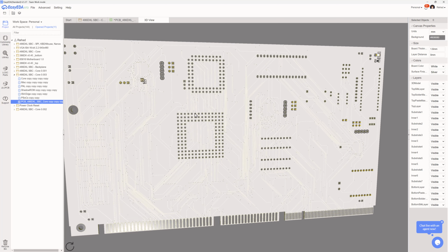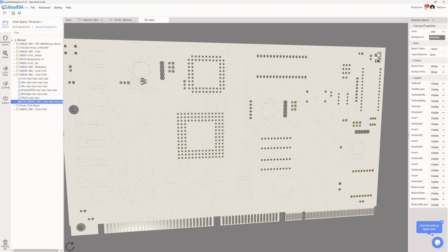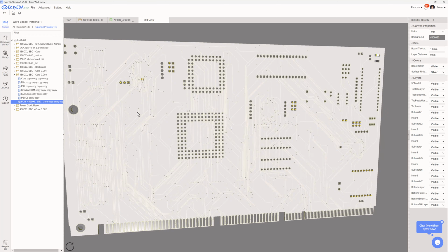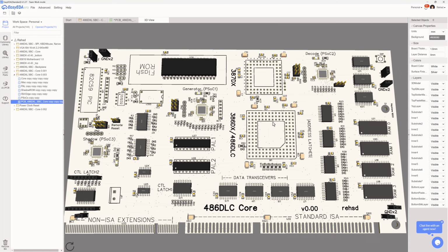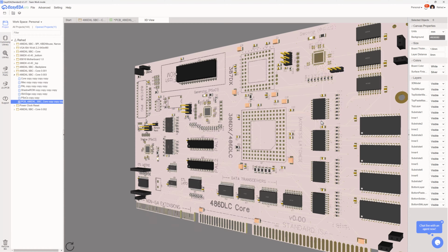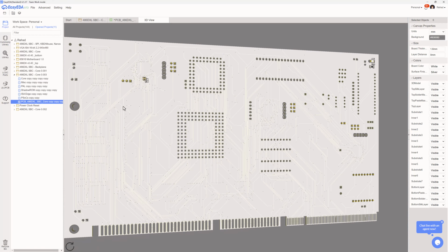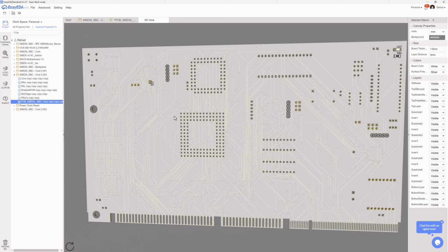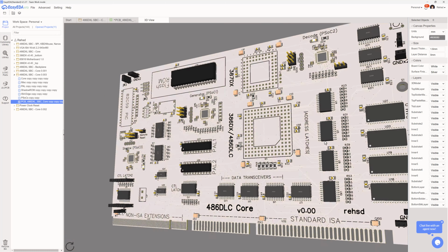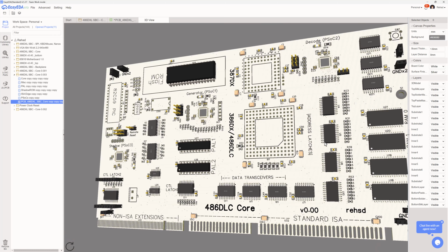And it looks like I've got a couple of straggler components I need to move back over to the front. But I did experiment with moving things to the back, and I didn't find it necessarily helped me unless I was going to go to a higher number of PCB layers. So for example, I did try to take these here and place them on the back somewhere in this region.